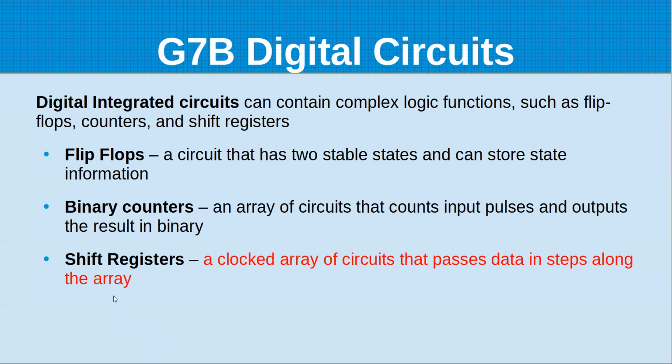So it basically shifts the value of that input through the shift register. So if you had an 8-stage shift register, and you start off with a 1 on the input, every clock, it's going to move that 1 to each stage until it falls out the end. And normally you could do something with that, like start it over or use it as some sort of overflow.